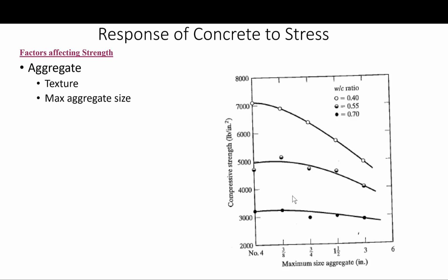All right. The use of maximum size aggregates affects the strength in several ways. Under compressive loads, the larger aggregate particles tend to cause a greater stress concentration and a resulting reduction in compressive strength. Also, larger aggregate particles provide more restraint to volume changes in the paste and so may induce additional stresses in the paste. So you have to be aware of all these variables, which basically in this case may weaken the concrete.